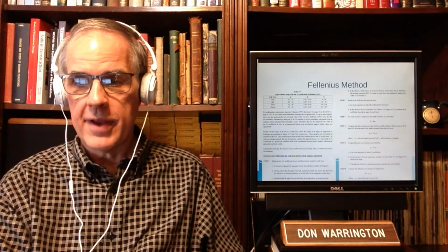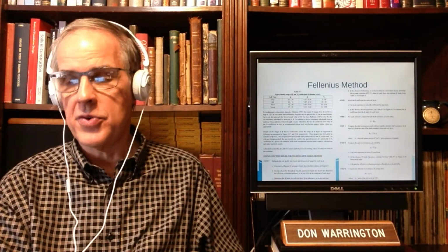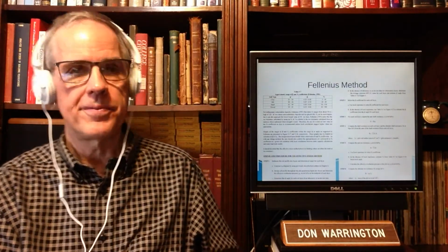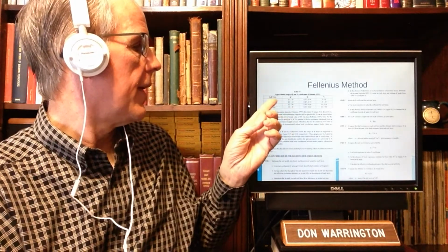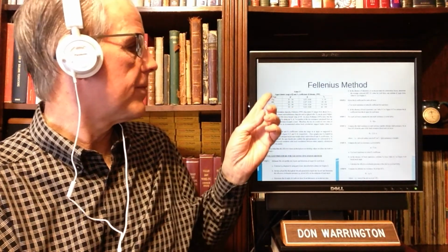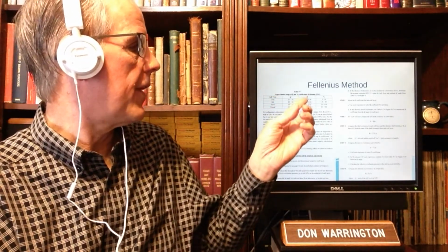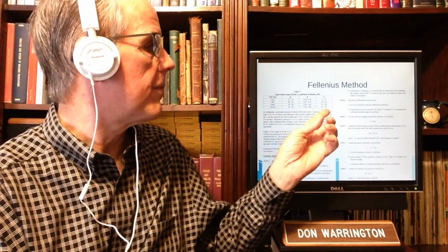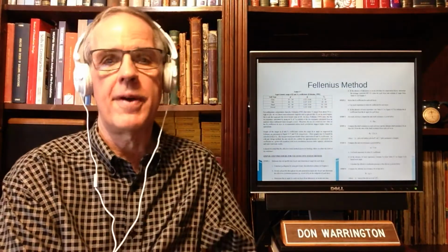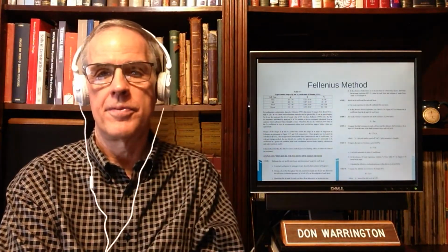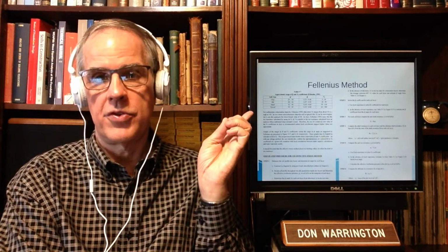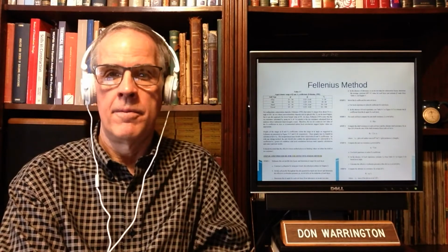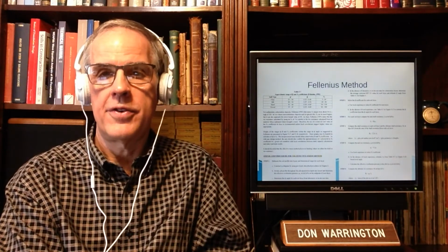Fellenius, basically, there are two ways the book shows how to do it. One of them is this table 9-7, which for given soil types gives different ranges of beta factors and ranges of bearing capacity factors at the toe. You can use that to determine your little fs's and your little qt's.